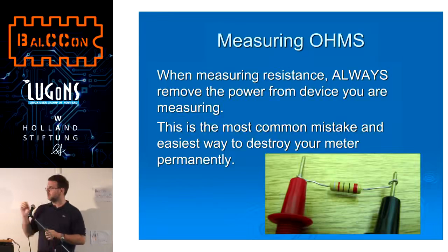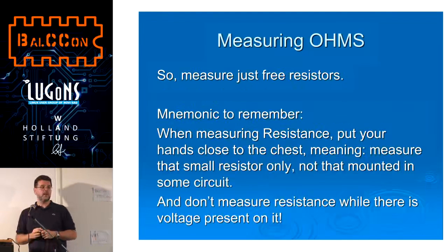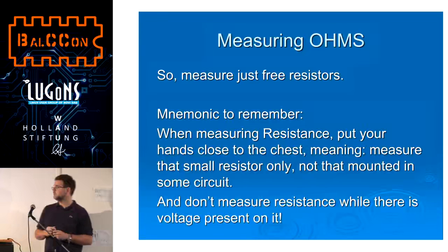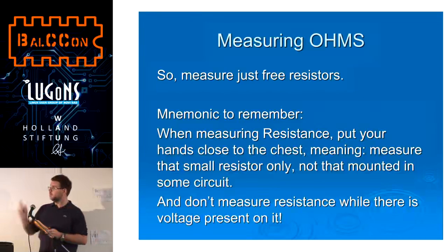Also, the resistor must be unpowered. And the most prevalent source of damage to multimeters is frying the multimeter when measuring resistance when the device is powered up or the resistor has power on it. So only measure resistors that are not powered.